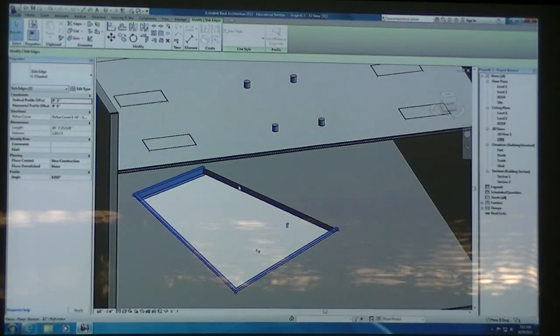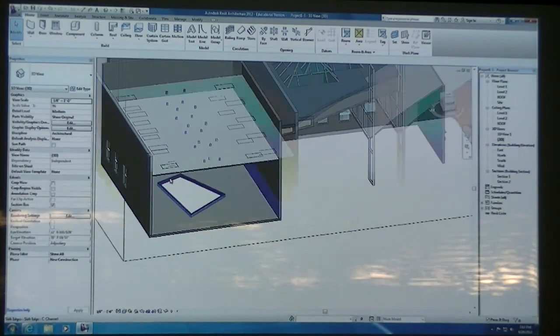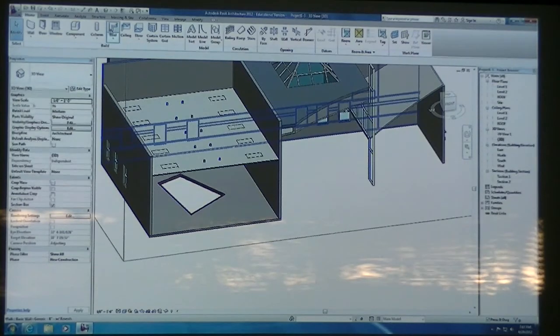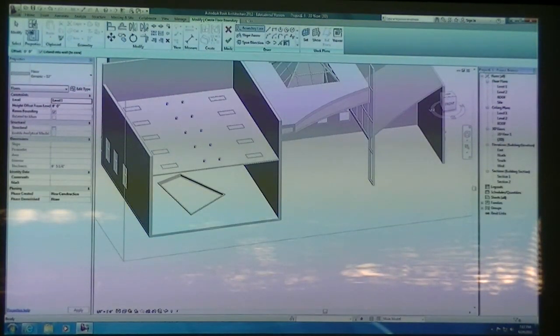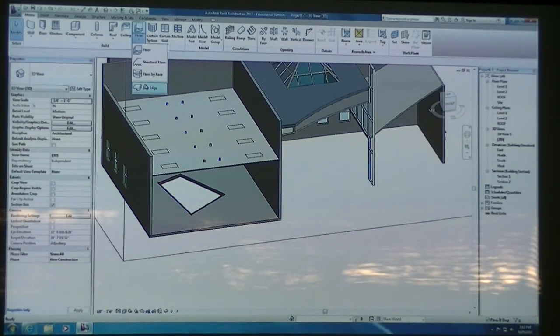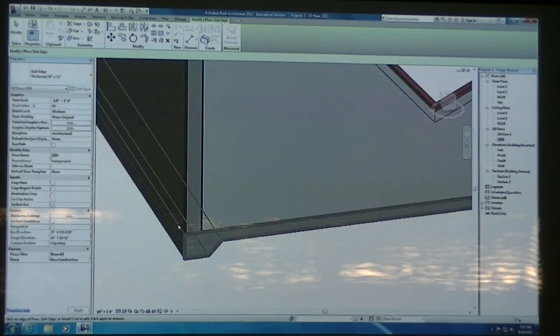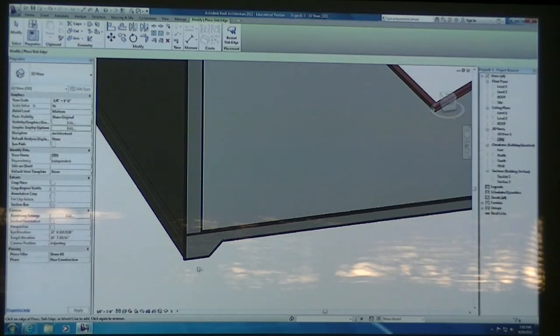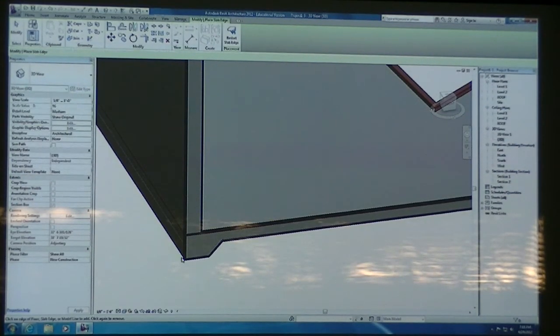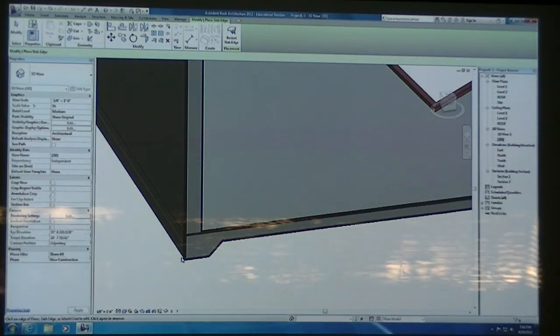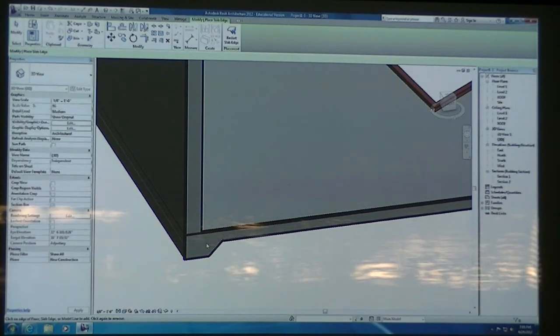So I'm going to add a segment again, and I'm going to add this segment back. Now that would work the same as if I had a floor, and if I do down arrow floor slab edge, and I do this thickened slab, and I can select this other corner here, you can see how I get that slab edge, that turn down that you normally see when you look at a section of concrete slab on grade. When you get to the edges, they always turn it down a certain distance, because usually you have a wall that's bearing on top of it. You need some additional reinforcement underneath there.